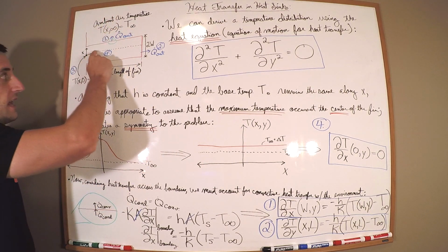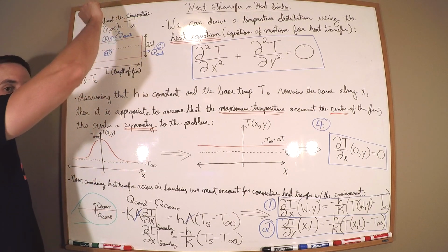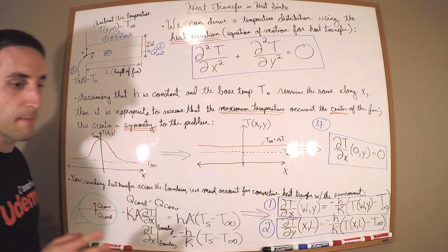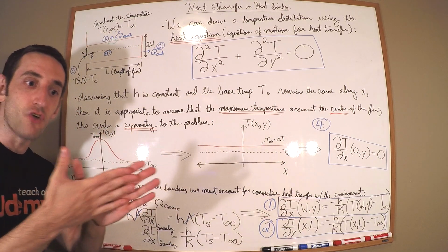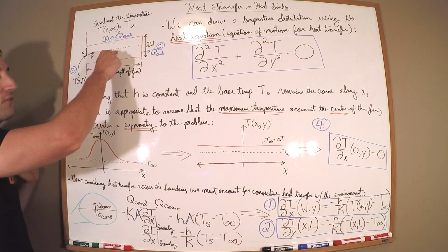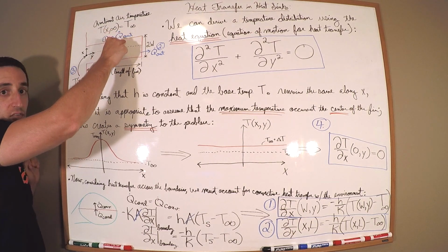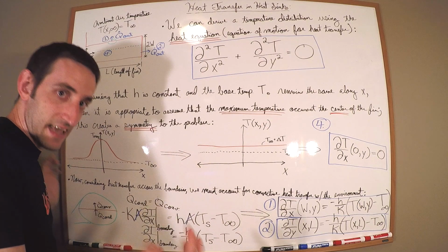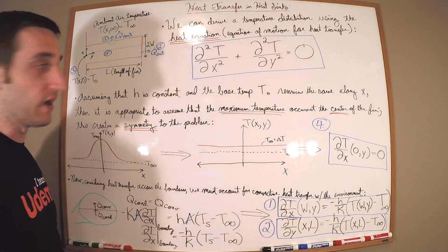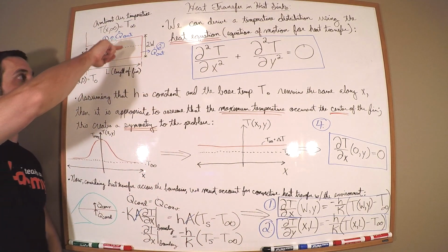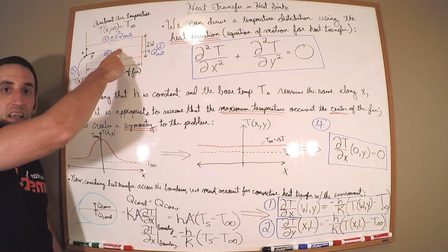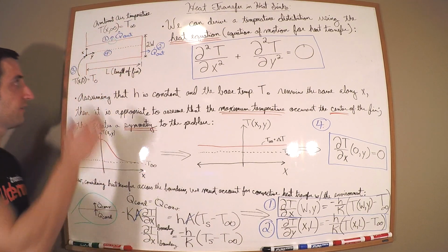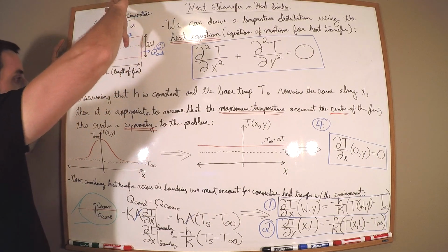Energy wants to flow in and then out, okay? So that means that if temperature gradients drive that heat transfer, the temperature has to drop as you move towards this surface, right? That is the physics. That is what's dictated by our heat transfer equations, okay? So if it has to drop in order to drive that heat transfer, this has to be the maximum, because it's not going to flow into the center. It's flowing in and then out.